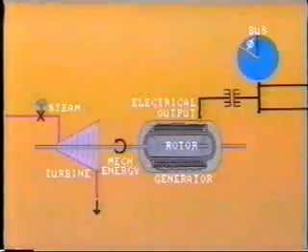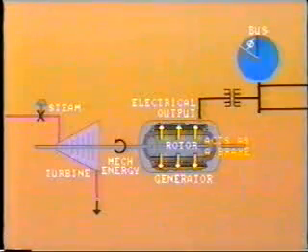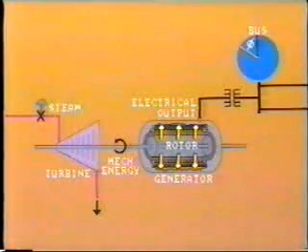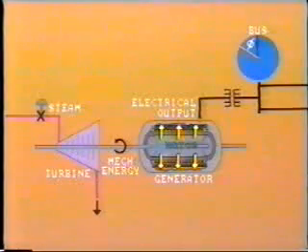When electrical load is applied to the generator, more current is drawn, consequently increasing the magnitude of current flowing through the stator windings. This current creates a flux which tends to act as a brake on the turning action of the rotor. In order to maintain the machine's speed and restore frequency, more steam must be supplied to the turbine in order to increase the mechanical output. All of the mechanical energy of the steam is transferred along the turbine shaft into the generator rotor.